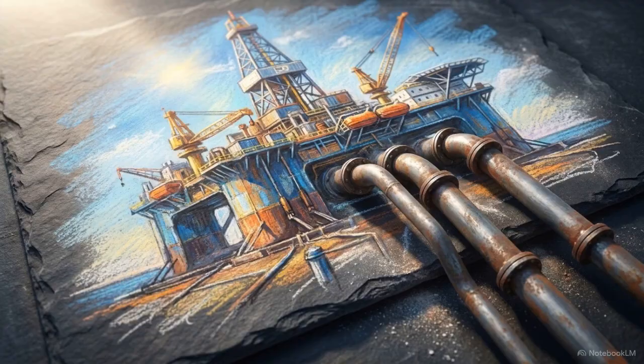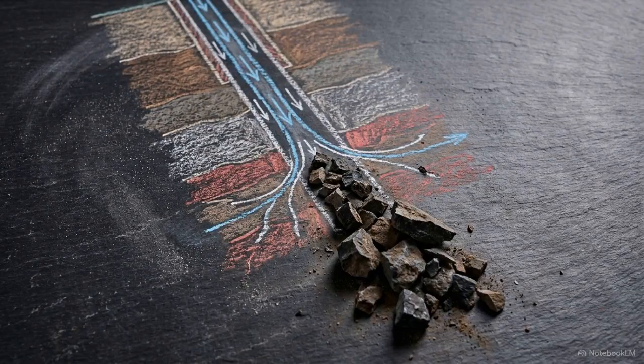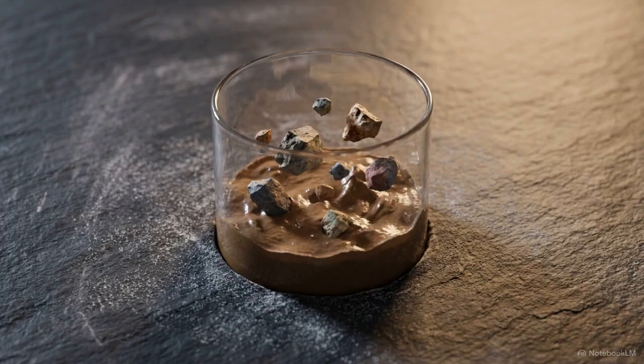At the surface interval, the system begins as an unweighted clay-water mud. Engineers mix bentonite into water to achieve high rates of penetration through the first several thousand feet. Because the system lacks high-density weight materials like barite, it has a low buoyancy effect on the drilled cuttings. Hole cleaning depends entirely on the fluid's internal strength, its yield point, and plastic viscosity.